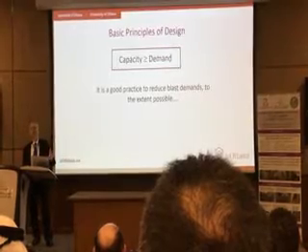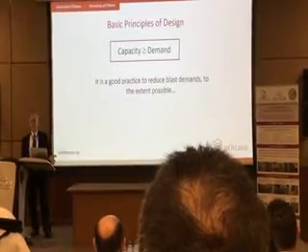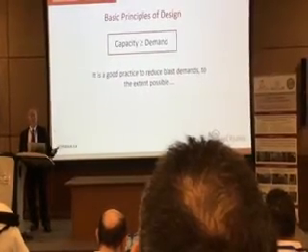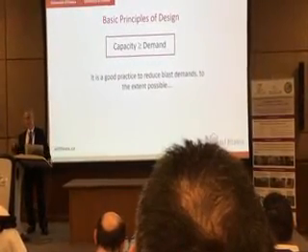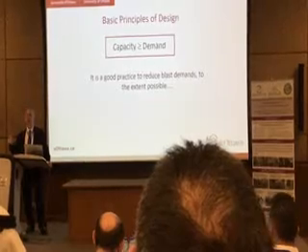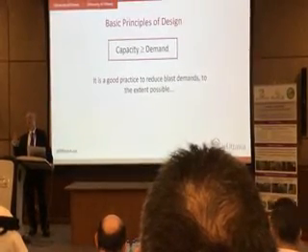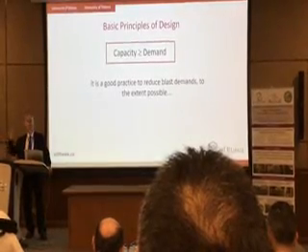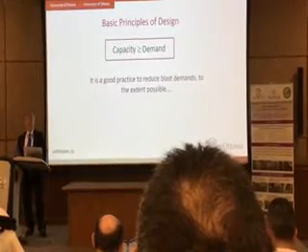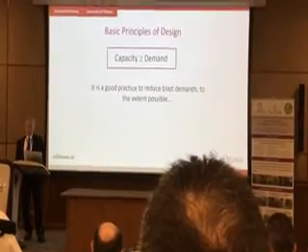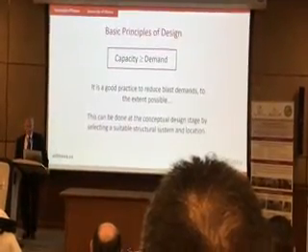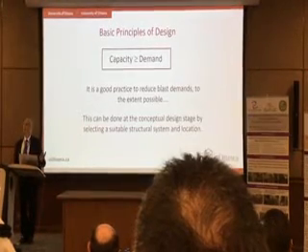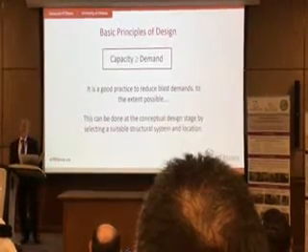But if you're designing a new blast-resistant building, then of course it's good practice to minimize demand. Can you do that? Yes, you can. As I already mentioned, if you have the right site selection, if you protect your building against intruders by keeping them at a distance, then that's the number one strategy. You have to pay attention to the location and selection. And this can also be enhanced by choosing an appropriate structural system at the preliminary design stage.